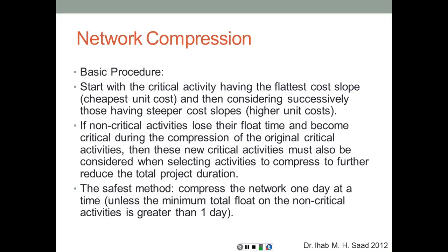The answer is both. Because if you compress one and leave the other, if you remember the definition of the critical path, it was the longest path in the network. So if you compress one of them and leave the other one, then the one that was left without compression is still going to be the longest path or the critical path, and we have not achieved anything. So if you're going to compress two paths, you have to compress both by the same amount at the same time.